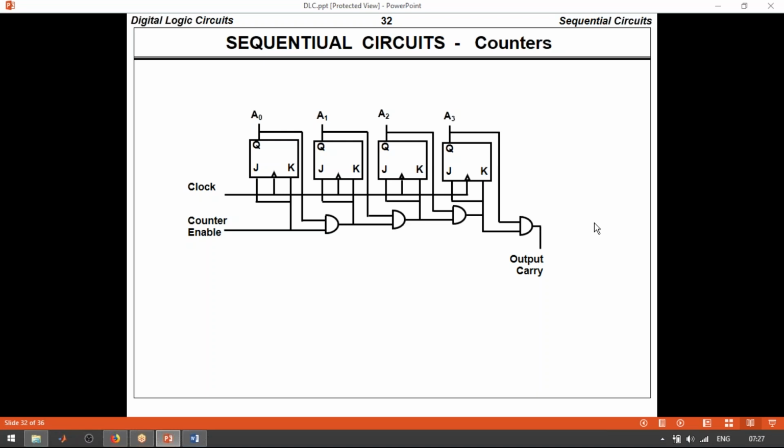That means the number of delays has been increased here for the next continuous flip flops. Here it is 0 1 0 1 0 1, and here 0 0 1 1, and here 0 0 0 0 1 1 1 1, then here 8 zeros and 8 ones.